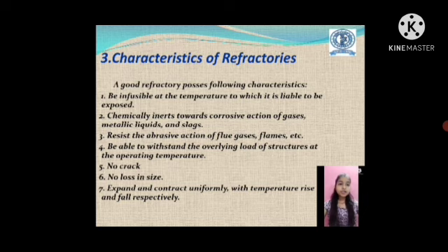Third, resist the abrasive action of flue gases, flames, etc. Fourth, be able to withstand the overlying load of construction at the operating temperature. Fifth, no cracks. Sixth, no loss in size. Seventh, expand and contract uniformly with temperature rise and fall respectively.